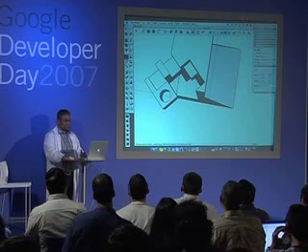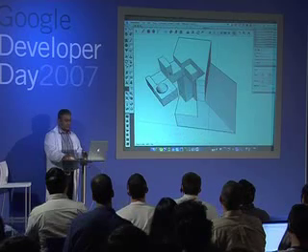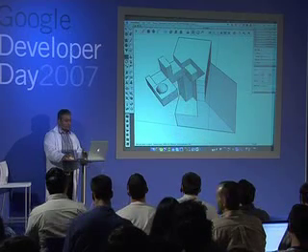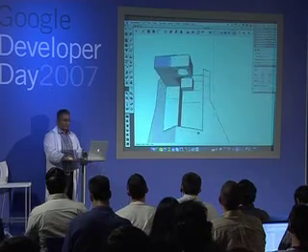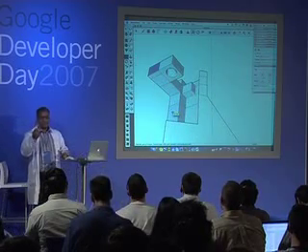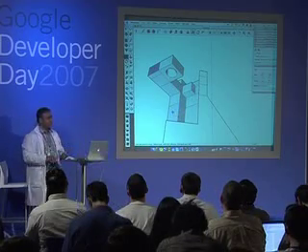So if I select that circle, I can move it. Okay. If I select its quadrant point, I can make it bigger or smaller. Okay. It works like you have a pencil. Just, I want it to be this big, this size.